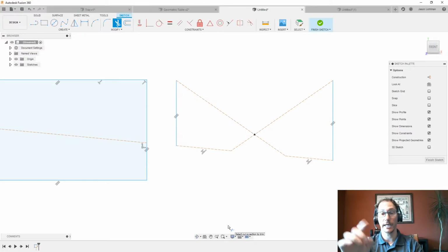Again, that's just clicking and dragging around. And it's basically like running around with scissors, I guess. When you were a kid, your parents probably told you not to run around with scissors, right? To be very careful about using scissors. So if you just click on the individual lines, it's like being very careful and snipping exactly what you want. And if you click and then drag, it's like running around with scissors. Just be very careful, just like you would in real life. So be really careful, but it is very fast in Fusion to be able to trim quickly. So that's the trim tool.